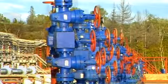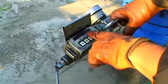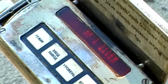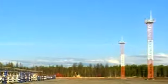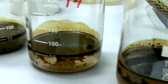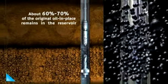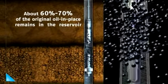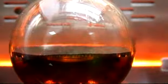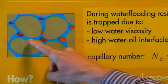Injecting water over a regular pattern of injectors to drive oil towards a pattern of producers represents a traditional enhanced oil recovery, or EOR technology. However, the process of displacing the oil with water is not efficient enough because oil and water are incompatible fluids. About 60 to 70% of the original oil in place remains in the reservoir and cannot be recovered by water flooding. A promising EOR method is alkaline surfactant polymer flooding, or ASP.